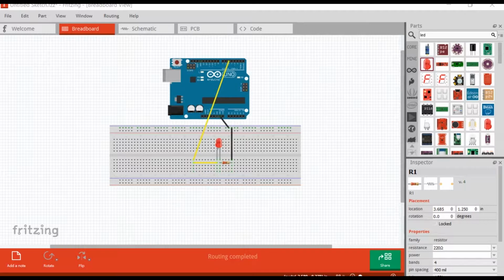So in this case, let's start with a circuit. As we can see here, the requirements for this project: we need an Arduino Uno, an LED, 2 jump wires, and a 220 ohm resistance. Okay, we need a 220 or higher. I'd recommend up to 1K.